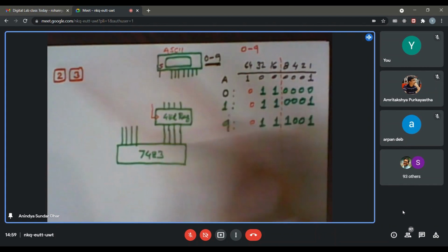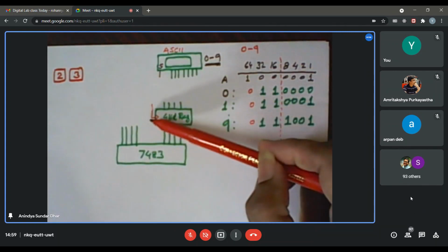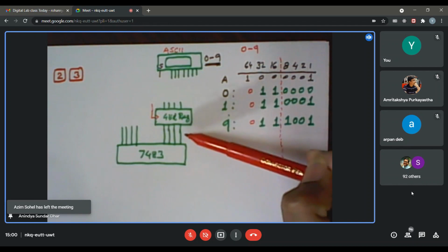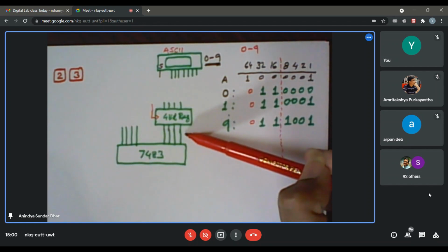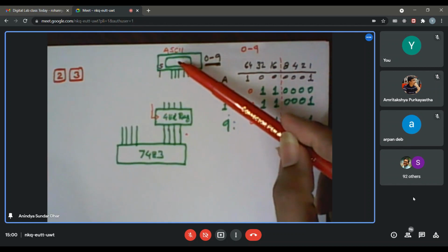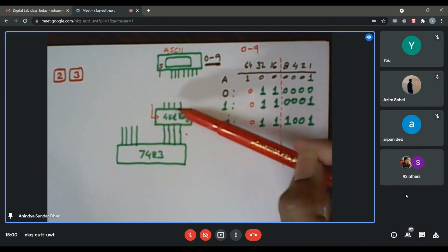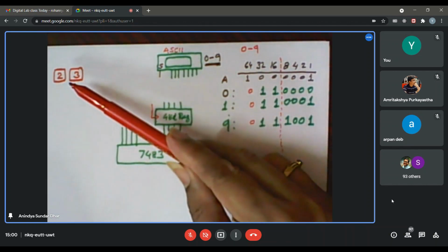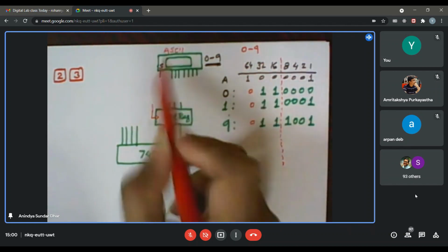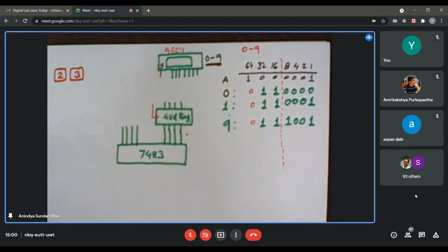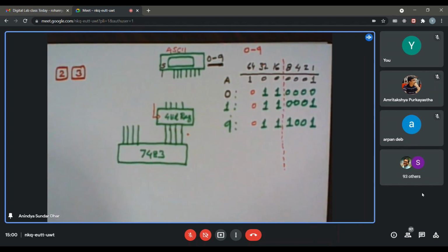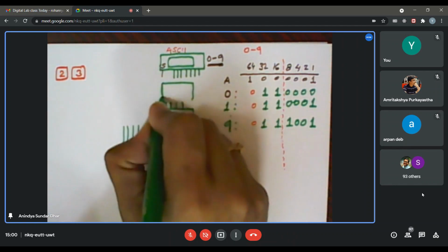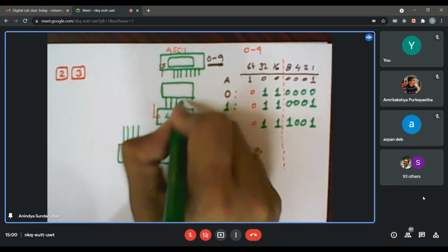So as soon as I press the first key 2, it will generate a strobe, right? So it will provide a strobe to the register. 2 will be stored, so the output of this one will become 2. Now, if I press 3, the strobe will once again come and 3 will be stored over here. So it will forget about that 2. Whatever your friend is suggesting, there might be some other way of solving that also, but the easiest way is to put another 4-bit register just above this, whose output you are connecting to the input of this 4-bit register.